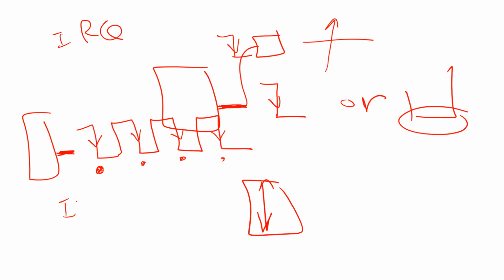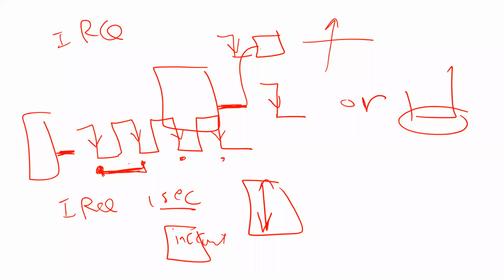So I'm going to enable IRQ for 1 second. Inside the IRQ interrupt, I'm going to increment the counter. Every time it is interrupted, I'm going to increment the counter. I need to know how many falling edges are in 1 second, because every falling edge is 1 cycle. And this is the definition of frequency: how many cycles in 1 second.